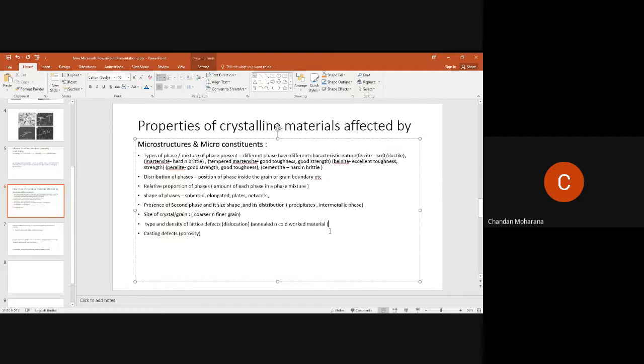A dislocation is moving, then it comes in contact with two second phase particles. The second phase particles pin the dislocation at both ends. Then you apply more stress. The dislocation cannot move because it is pinned by the two particles at both ends. Then it will bulge out slowly, and finally it will form a loop. This loop will come in contact with itself, and the moment it does, a new dislocation will generate. But the initial dislocation remains pinned there.